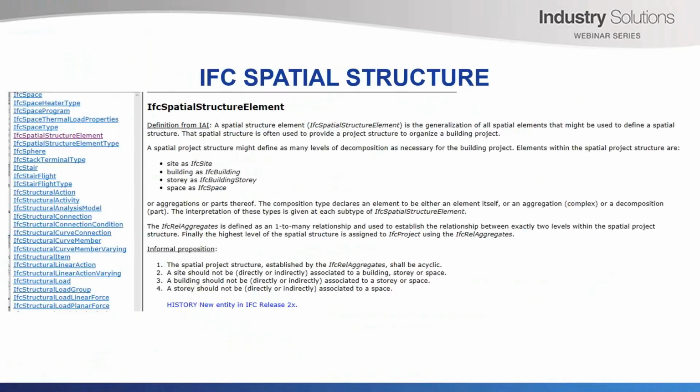But you need to know about spatial structure, but most of our users at the moment just put out everything as IFC site because it doesn't really fit into a building or a story. What the IFC space is all about, that's really for inside buildings where instead of having a perfect representation, it's just like a block model, so you can work out, say, the volume of a room and things like that. So you need that to go into, say, facilities management systems. So you tend to draw up things and just approximate the room by a couple of rectangles, and that's your IFC space. So it's not a real physical object, it's sort of like an area.